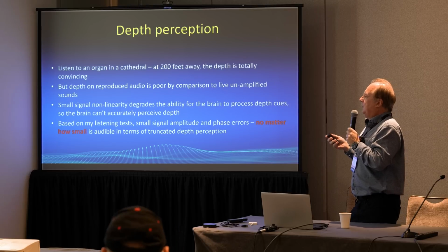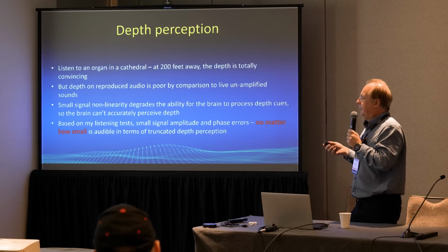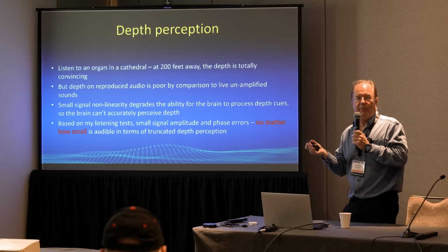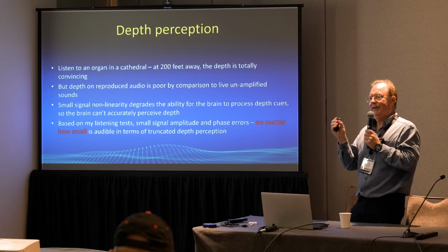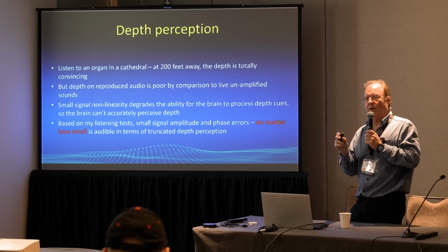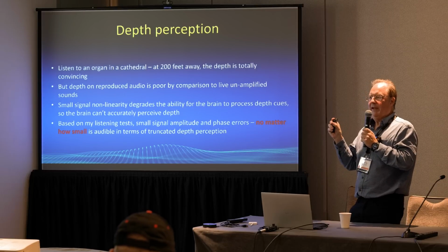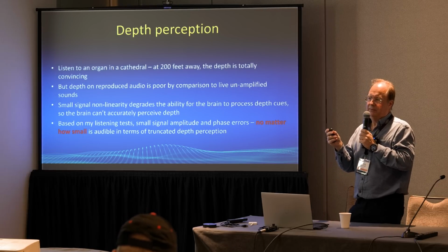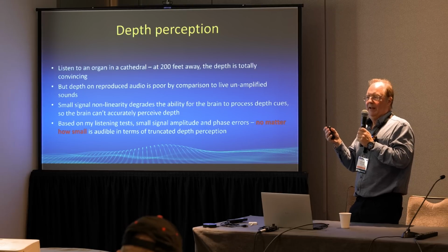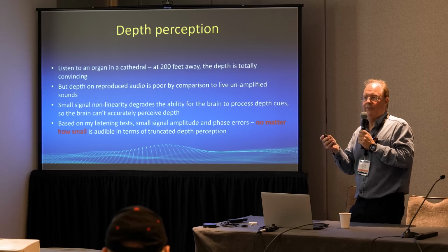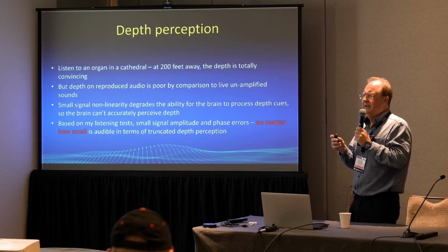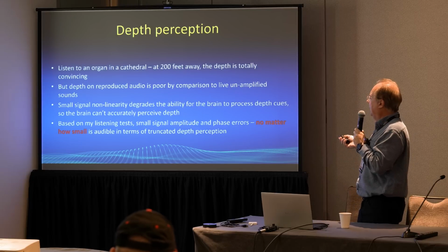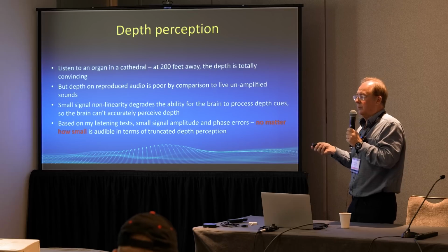What I found is that small signal nonlinearity really is crucially important. And one of my tests is to use something called a minus 301 dB signal. So all my digital parts are tested in simulation with minus 301 dB. If there's a slight error within a thousandth of a dB, it's audible. If there's an error in the phase compared to 0 dB, and here we're looking at a thousandth of a degree in phase, you can hear the difference, which is pretty damn staggering, because it makes no sense that we need this level of accuracy. So again, no matter how small the error, it's audible.